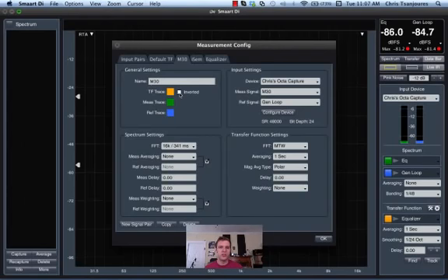You can choose to invert the trace, which is what I'm going to do for the equalizer, because when I do a gain or boost, I would like that to show as inverted, so I can do a cut and have it show up as a boost in Smaart, so that I can actually match the equalizer trace to the magnitude trace. So that is an exception. Live measurement, you typically would not invert the trace.